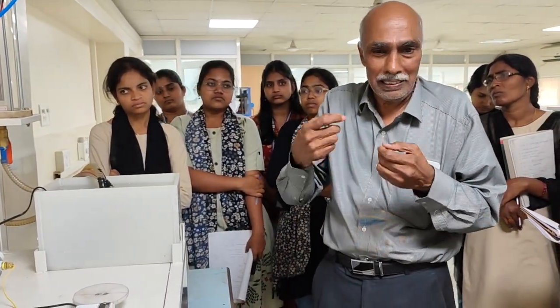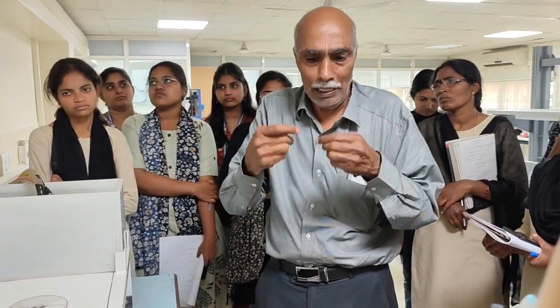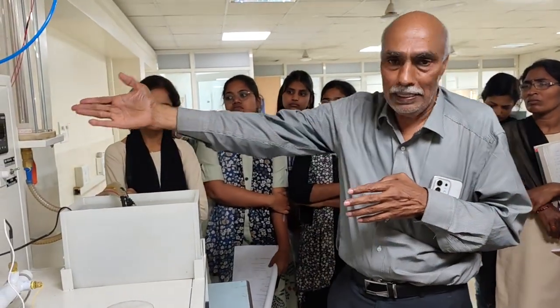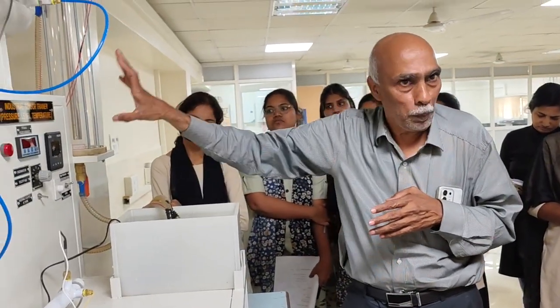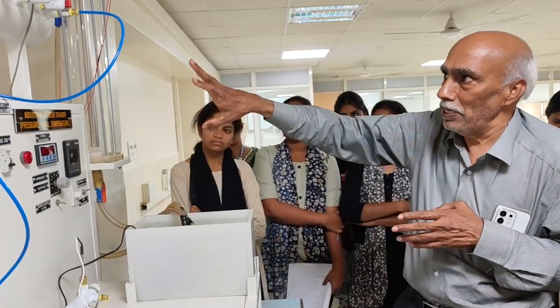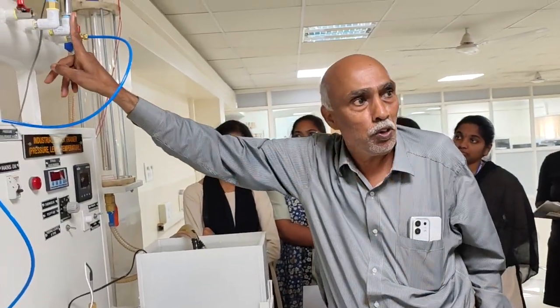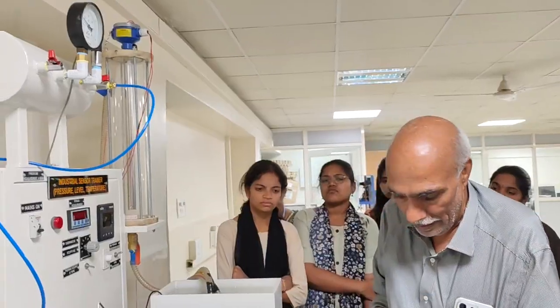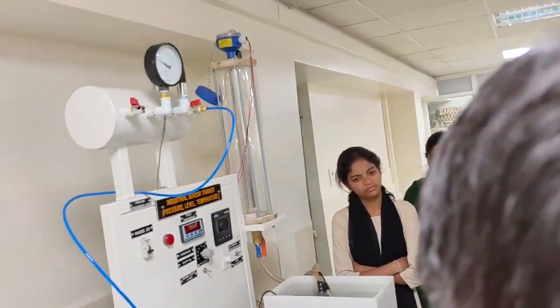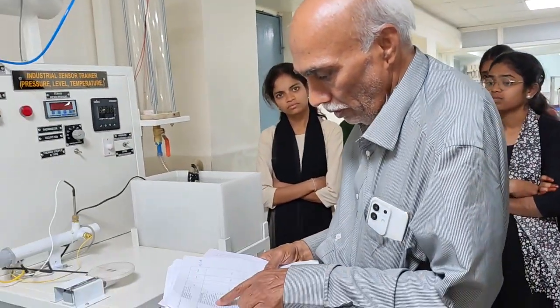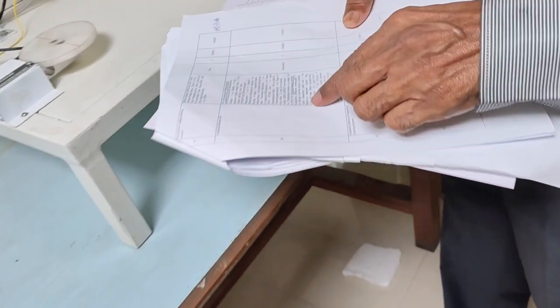It has certain electronic components, certain sensor output is coming, registers are there, so many things are there. There will be some losses. Because of the loss, the meter is bound to give some error. So that error needs to be nullified and set according to the basic system. So whatever the pressure is coming out from the sensor, the output from the sensor is in milliamps. For example, here as per the purchase order, this is giving 4 to 20 milliamps output. You can see the industrial pressure sensor, the 4 to 20 milliamps output is there. You have to study the 4 to 20 milliamps output.